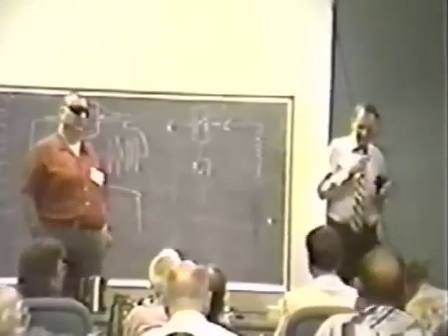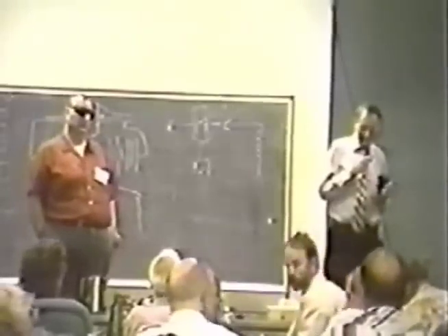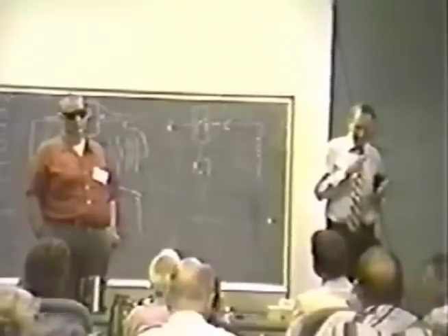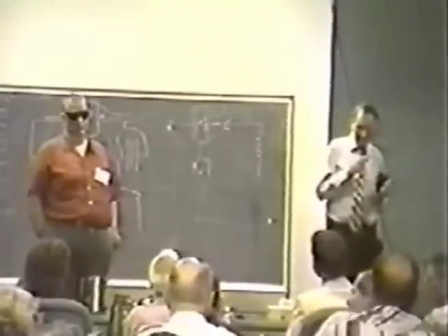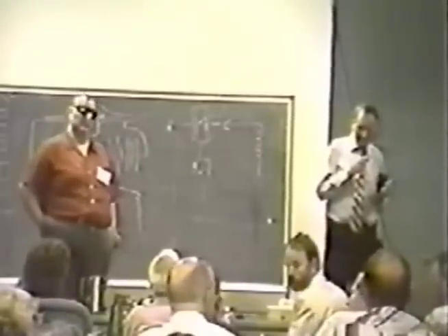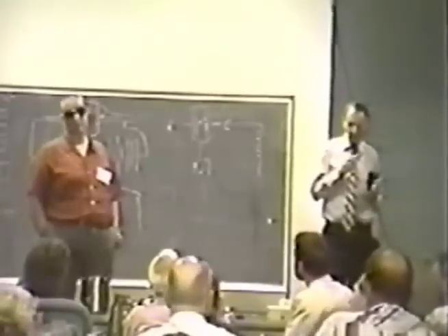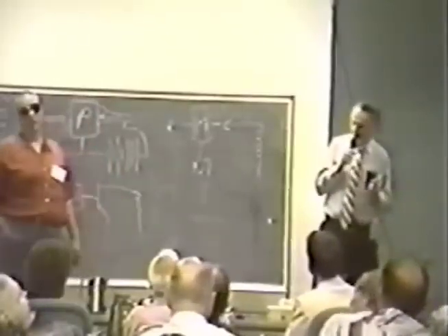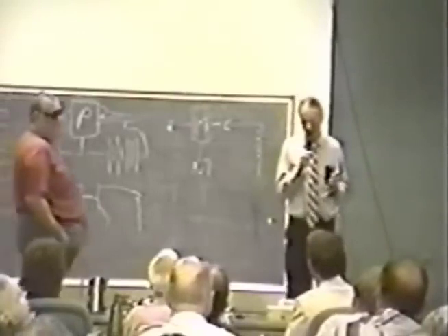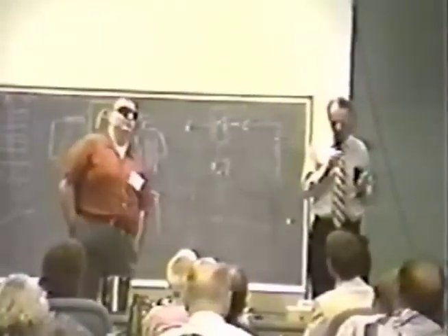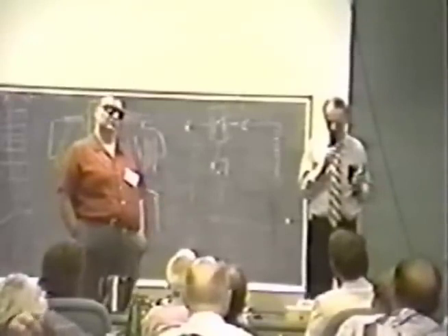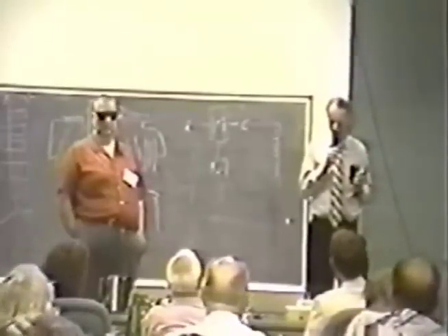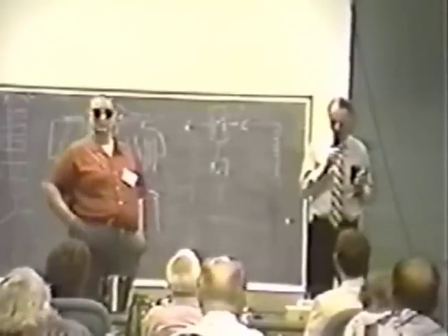Just a comment. My experience with those type of devices, those type of diodes and transistors, is that they're very sensitive, and if you place them in a properly machined cavity, you can get bandwidths up to 300 gigahertz. Yeah, I know. Gunn diodes, right. They seem to have disappeared from the market. There are many things you can do with the properly built germanium devices you cannot do with silicon. And this is a technology which has been almost forgotten and buried, but probably not in certain government circles.